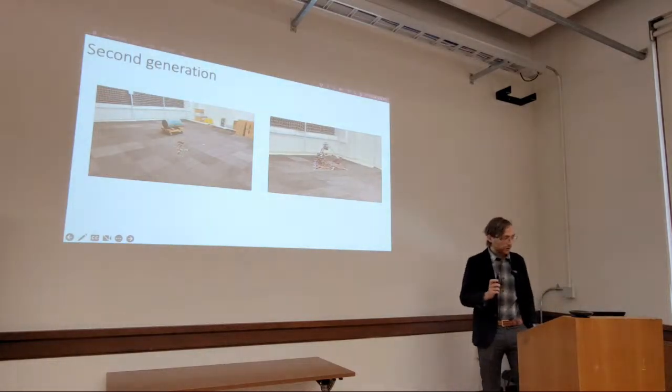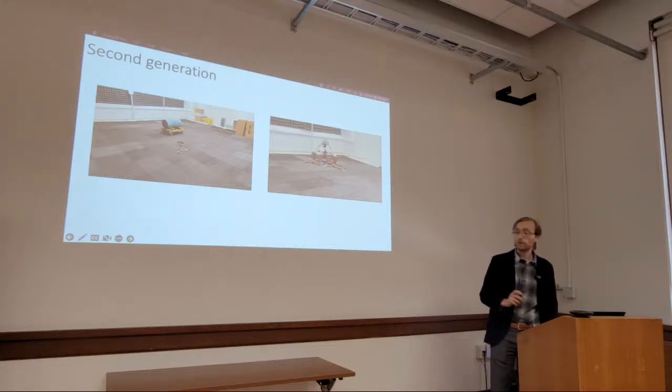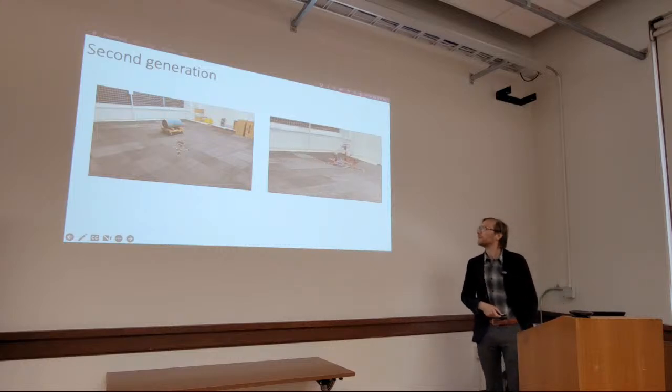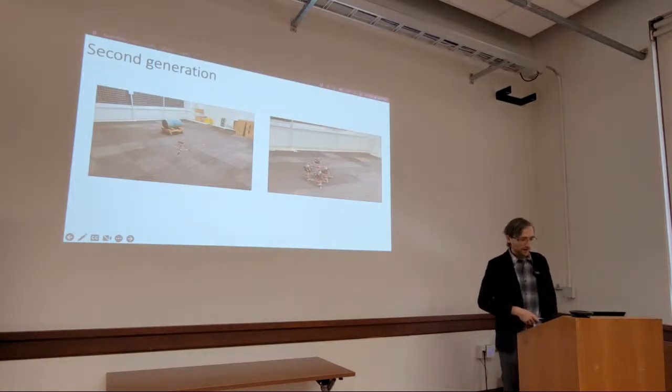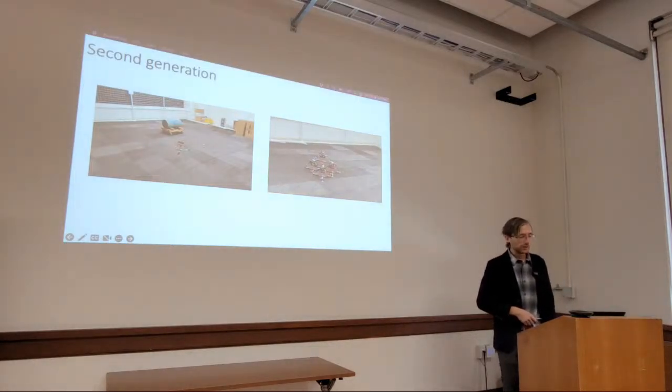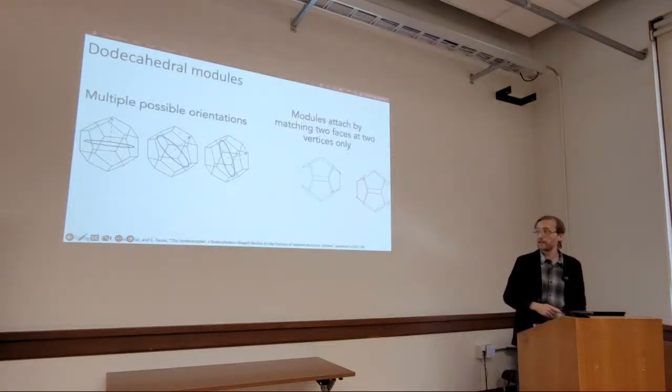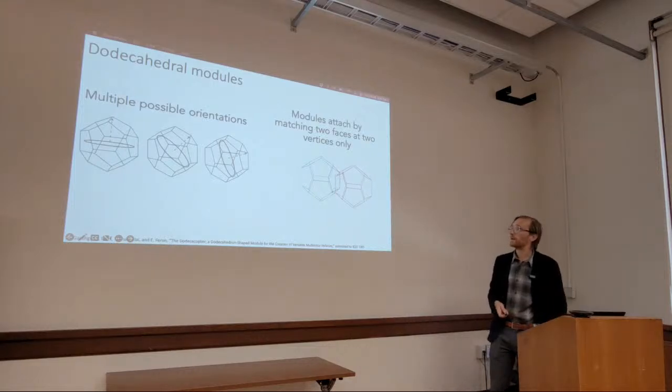But I also mentioned the fact that we may want 6 degrees of freedom vehicles, and we cannot do that with this tetrahedron shape, or at least not easily, and certainly not efficiently. So what I tried to do next is come up with a different type of modular vehicle where we could also build 3-dimensional assemblies in order to have good structural properties, but also be able to orient the different propellers in different directions, such that 6 degrees of freedom vehicles can be constructed with this module. And so that's the next module I came up with.